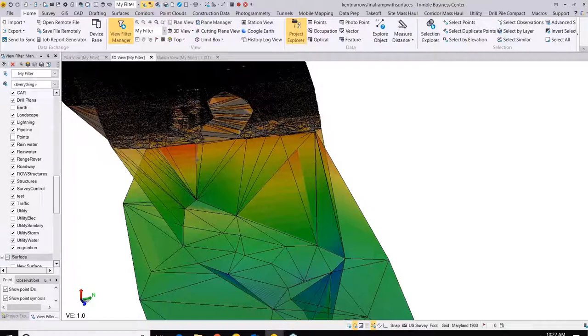My thing with doing the RTK readings on this is that it's a completely different process than the way I did it. When you bring an RTK into it, there's a different sheet that comes out, the one that has the depth applied and attributes, and it gives you a percentage. The first thing you have to do with an RTK is go through and take out anything under 40% and drop that out. It's not giving you an actually good reading. Anything over 40% you want to keep.